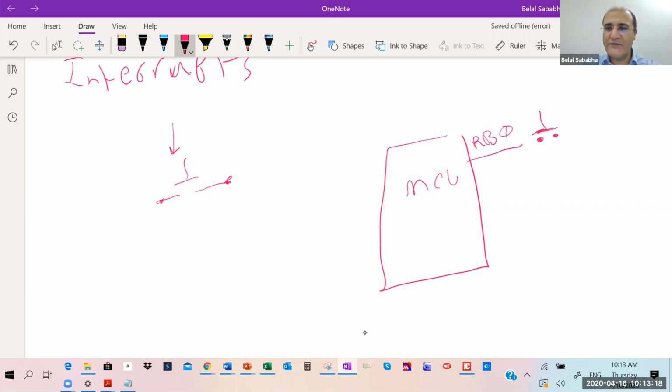Last time when we started, we did not use the pull-up resistor. So it was port B0, connected like this, without a pull-up resistor. Well, let me make it better. Let me draw it as a pin. It was connected like this, and this was connected to VCC.